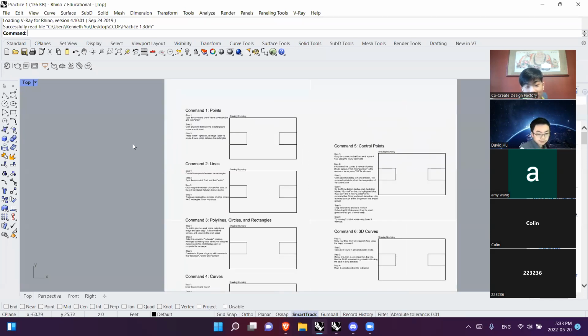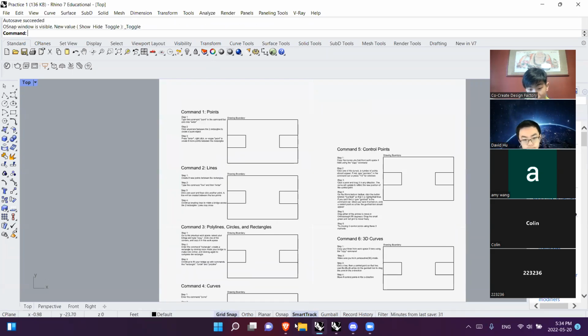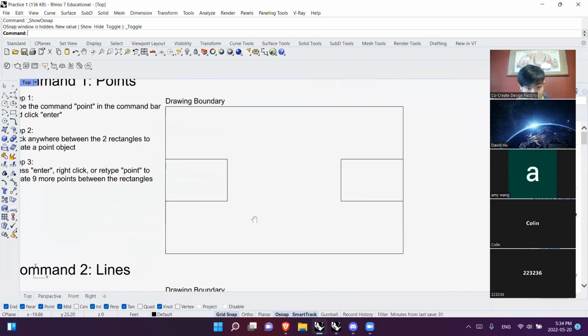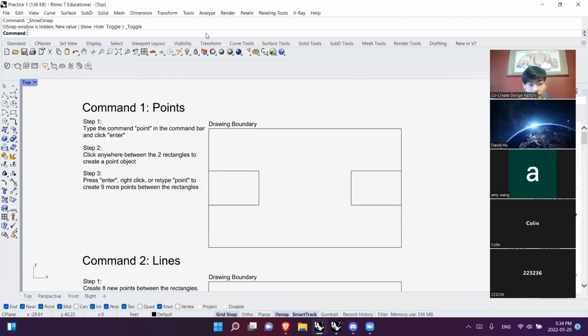So basically all we worked on last time was, first of all, how you can get the software. And then we went into all of the basic settings that you need. I'm just going to do it again. If you're on Windows, you have these settings that you should turn on, which include grid snap and object snap. Then you just click all of these check marks. Make sure you have these settings on, because they make your life really convenient.